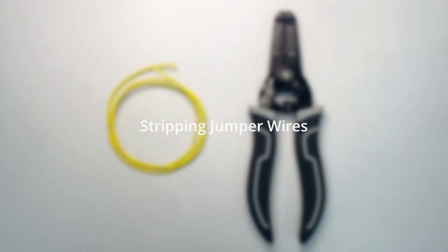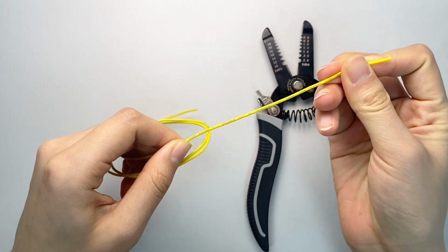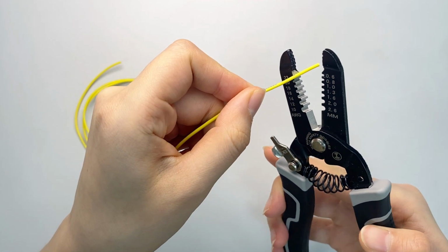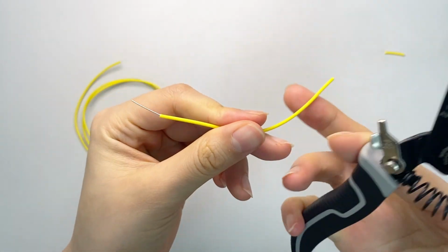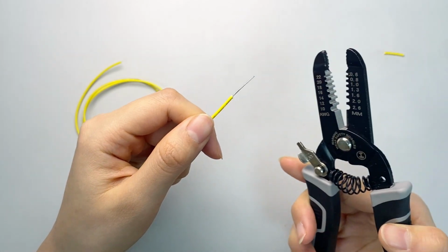Stripping jumper wires usually requires the following steps. Estimate the length of jumper cables required and cut them with wire cutters. Depending on the size of the jumper cable, select the appropriate notch on the wire strippers. Allow about 1 to 2 centimeters from the end of the jumper cable. Align the slot on the wire stripper and press down firmly on the stripper to remove the insulation from the jumper.